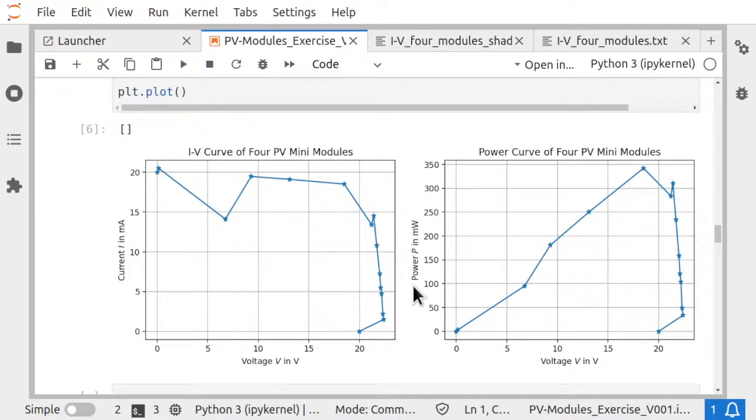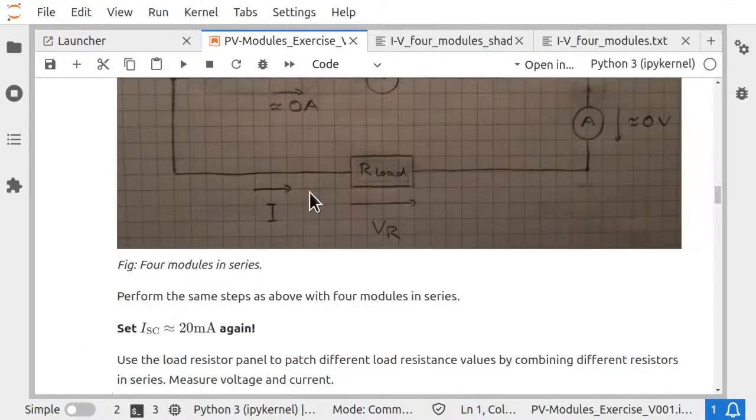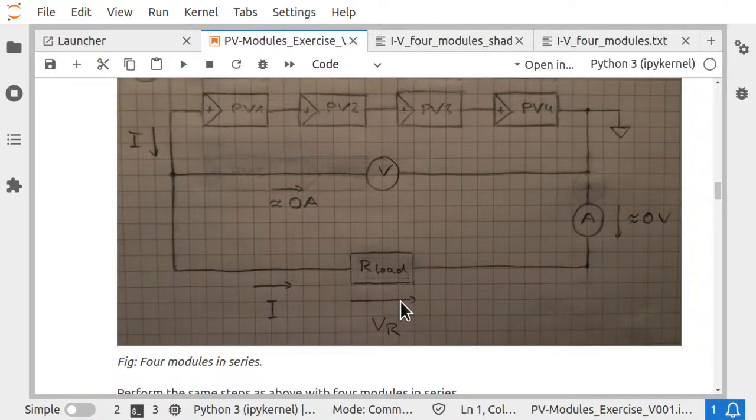So in a real PV generator system, a large one, you would use a so-called maximum power point tracker, where this load here is replaced with special electronics which sets the environment here such that the maximum power is extracted from that system. So it adjusts basically your working point dynamically.